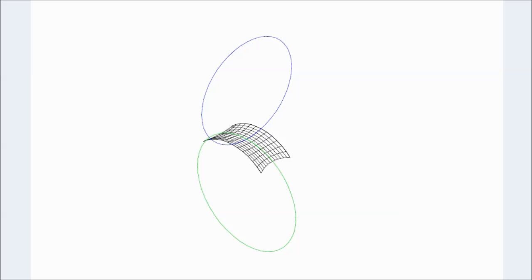When loads are applied, this could be wind suction, snow load, or any other natural stress applied to the structure, the load causes one of the hoop stresses to increase and the other to decrease. This change in stress will stretch or shrink the material, giving it a different structural shape. That, however, is a further complication which we'll ignore for now. At some load value, the structure will lose all hoop tension in one direction and will then behave, locally, as an inflated structure. This could be the point where large deflections start.